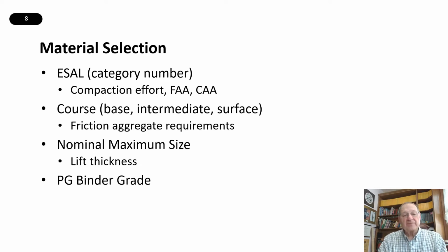The nominal maximum size is typically related to the lift thickness, but that's a given to us in terms of what nominal maximum size we are to use, and then of course the asphalt binder grade that we are to use. So there's how we select the materials that we will use in putting together our mix design.